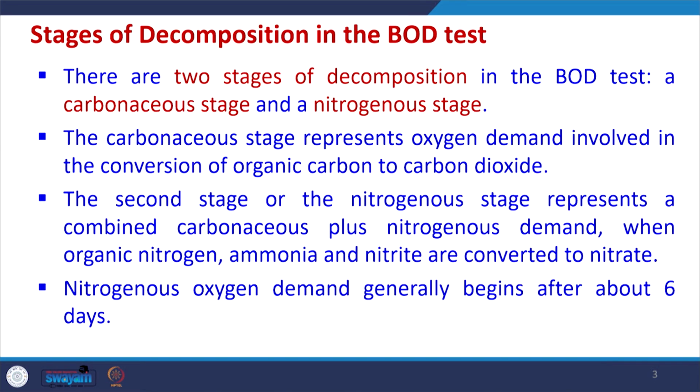During the BOD test there are different stages of decomposition. There are essentially 2 stages. One is the carbonaceous stage, under which the carbonaceous organic matter degradation happens, and then there is a nitrogenous stage under which the oxidation of nitrogenous compounds happens. The carbonaceous stage represents the oxygen demand involved in the conversion of organic carbon to carbon dioxide, whereas the second or nitrogenous stage represents a combined carbonaceous plus nitrogenous demand when the organic nitrogen, ammonia and nitrite get converted into nitrate.